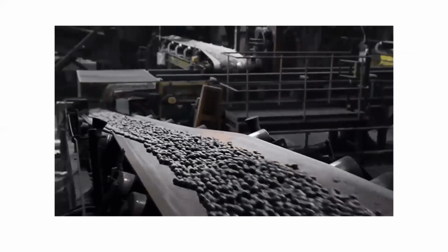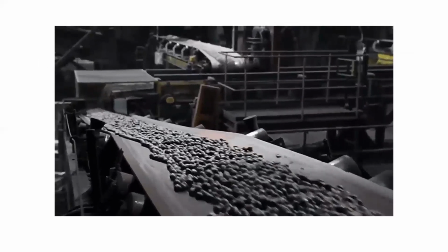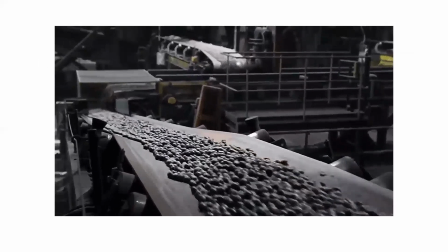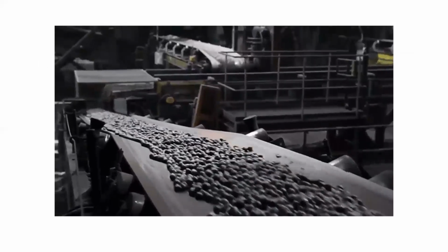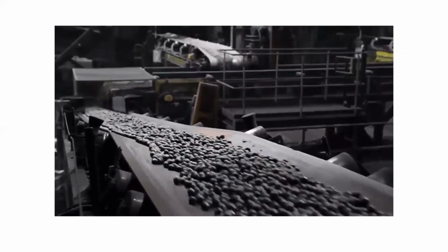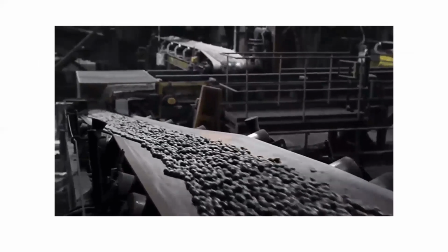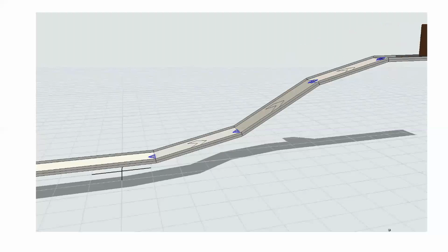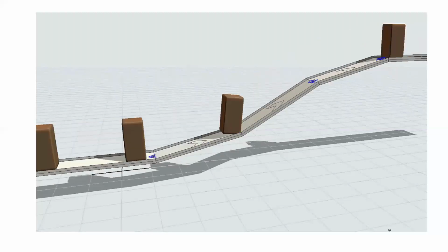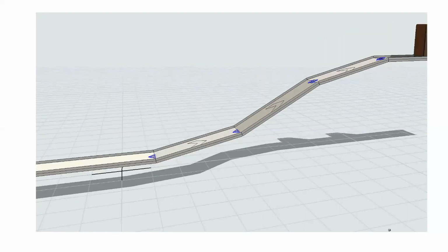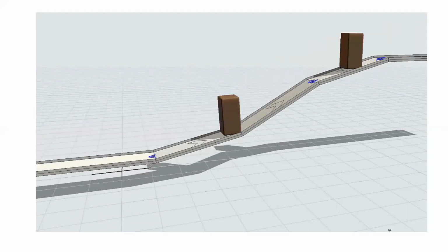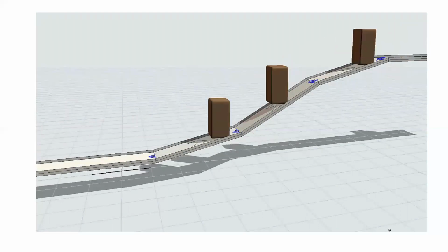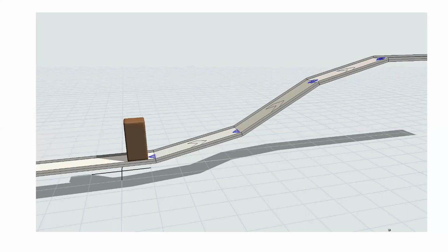Conveyor belt systems often are used in multiple ways to either elevate or to bring material to a different location. They often utilize more than one motor, and that's because of the way in which the conveyor belt system has to be designed for multiple direction changes. Especially when we are going up or down, there needs to be ways to have independent control of each conveyor section. And when we have equipment or materials on a conveyor system, the order of which each one of these sections is started will become very important.